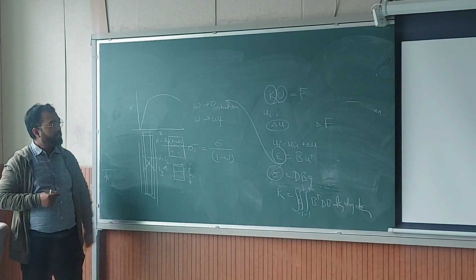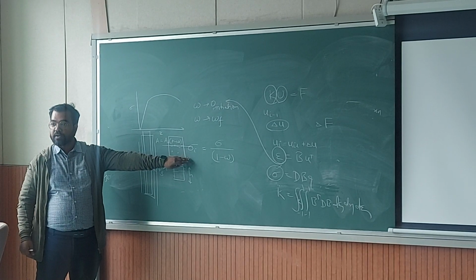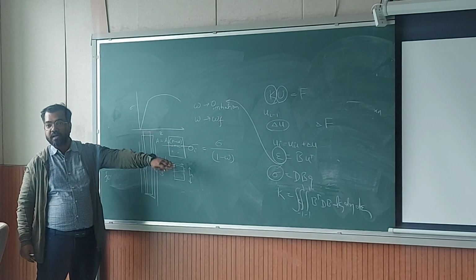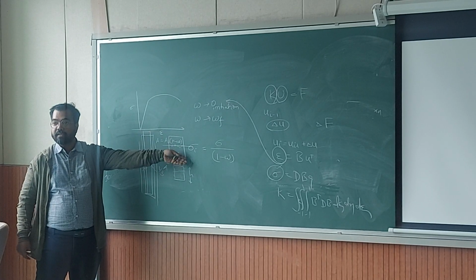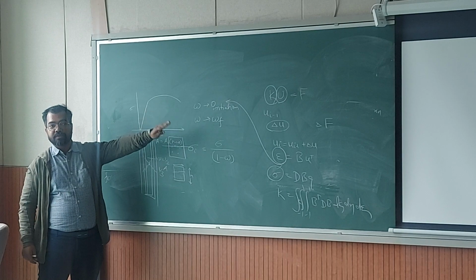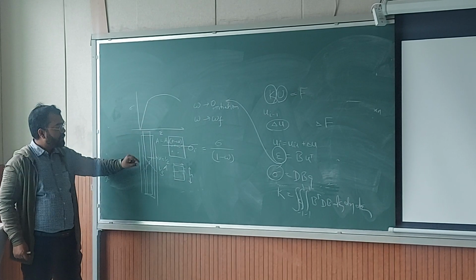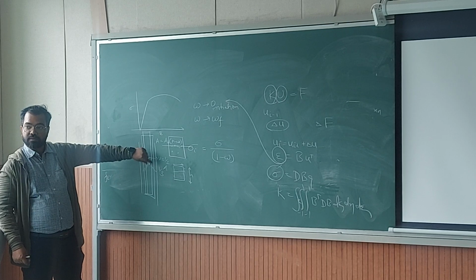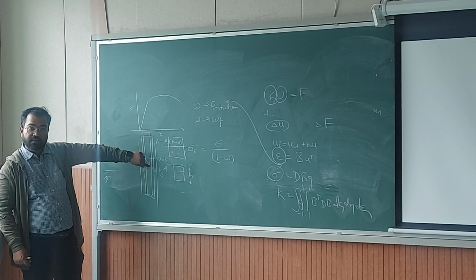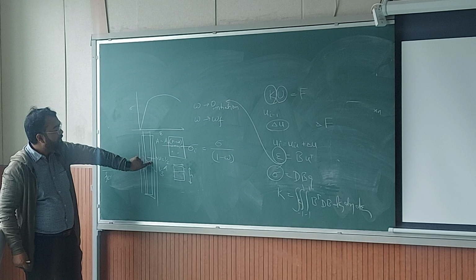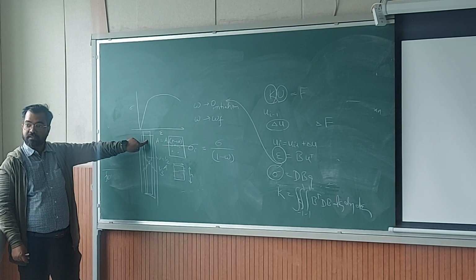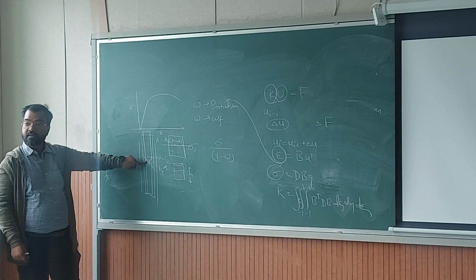And a lot of damage will initiate here. And wherever you have damage, you have higher stresses. That causes higher strain, that causes higher damage, that causes higher stress again, that causes higher strain again, that causes damage. So it will be a loop, and you will have more and more damage there, more and more stress there. So more deformation will be here in comparison to other places. So then it will start necking.